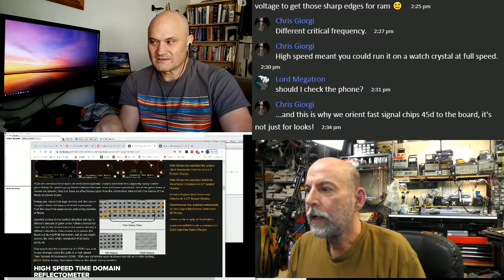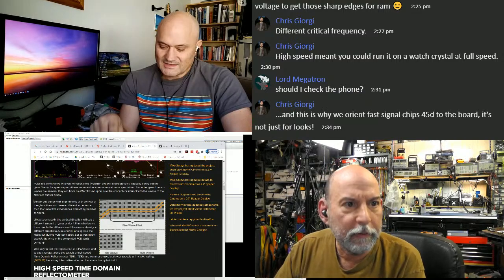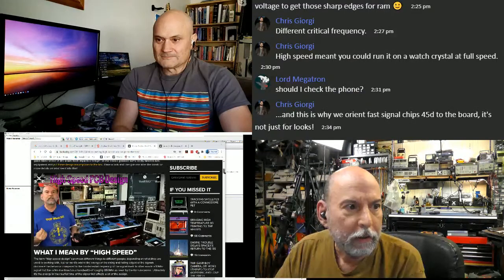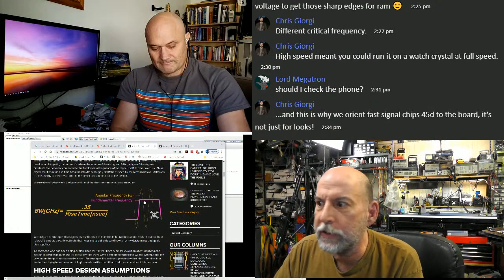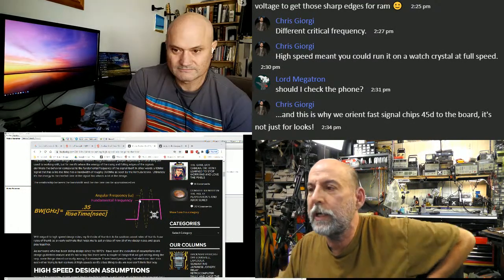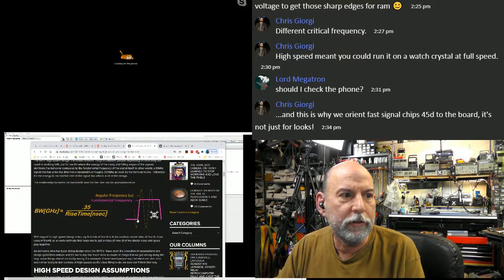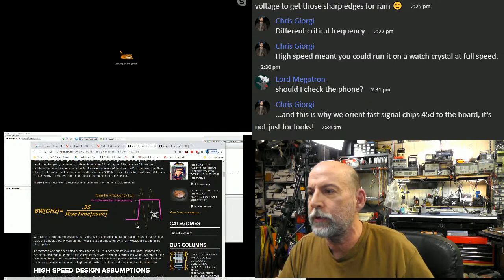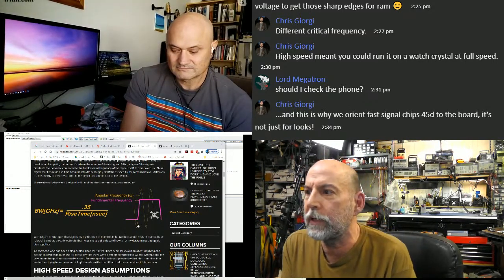Right. And ringing, if you count the time that a signal is valid, let me back up here a little bit. If this signal comes up here and then rings for 10 nanoseconds, guess what? That's 10 nanoseconds off the top. You don't count when it overshoots, and you don't count when it undershoots. So a ringing signal's slower than a signal that doesn't ring, for the logic.